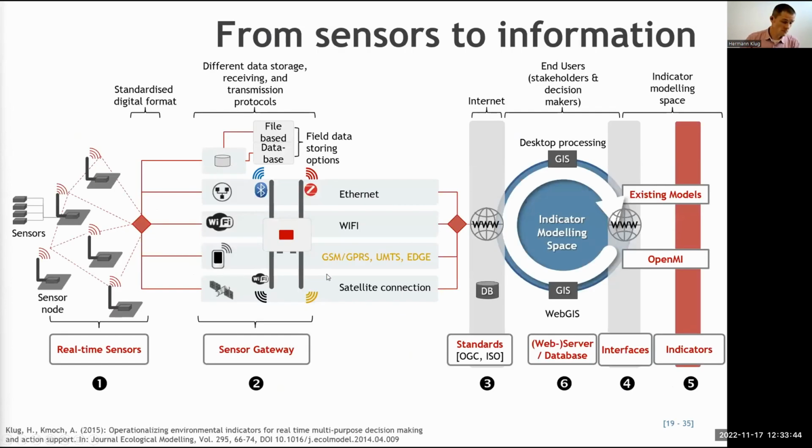And this is what I came up with as a structure. So we have a lot of sensors, like mentioned before, at one station. And these sensors are connected through wireless protocols. It could be LoRaWAN, but that did not exist in the beginning of 2011. We used Zigbee for that. Zigbee is a protocol like wireless LAN, operating at 2.4 gigahertz and operating 7 kilometers line of sight.